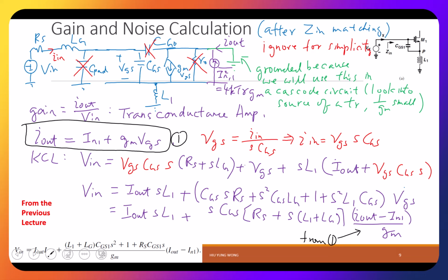Now, as I said, you should know how to draw the small signal model, right? So now we draw this one. This is the full circuit, or DC, right? So we draw small signal, gm VGS, I add everything: CGS, CGD, RO, which is the channel length modulation.